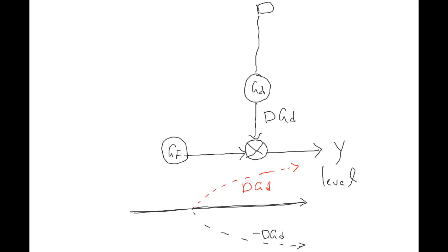So how do you do this? You have the transfer function of the process. In the transfer function, if the input change is a step input, just put the step input change and see how the level is building up. Accordingly, you have to open the valve. So how do you understand D into GD? It is how the level builds up with the disturbance.